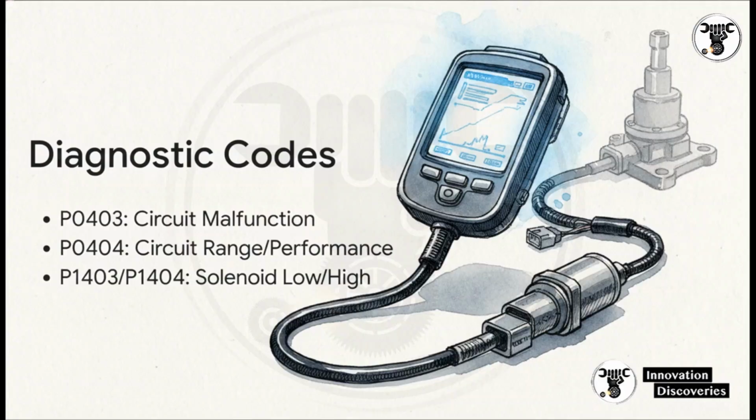Diagnostic trouble codes like P0403 for an open or shorted circuit, P0404 for range and performance, or those manufacturer-specific codes like P1403 and P1404. These point you immediately toward the electrical control circuit of the solenoid rather than a mechanical fault with the EGR valve itself. For you fleet techs out there, logging these specific P codes and standardized test results across your vehicles is a massively critical step in predicting systemic solenoid failures before they actually strand a driver.